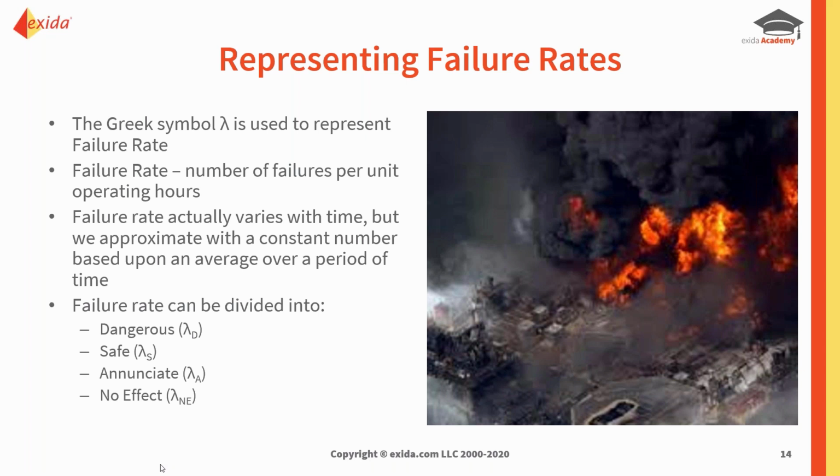If the instrument is operating normally, the control room operator can see the device, can read the current values clearly, but when you look at the LCD it is blank because the LCD has failed. That's an example of a no effect fault, because even though the LCD has failed, and okay, it's inconvenient because we can't see the reading in the field, the device is still functioning perfectly from a safety point of view, and the operators can see the values.